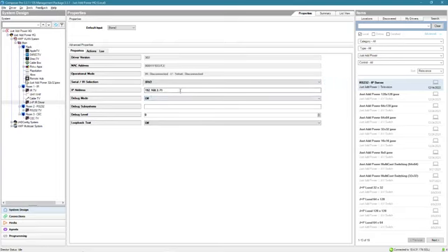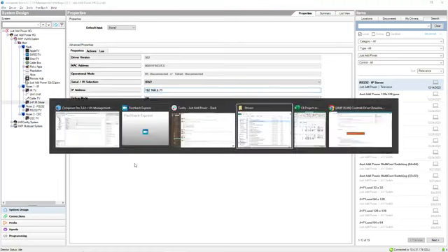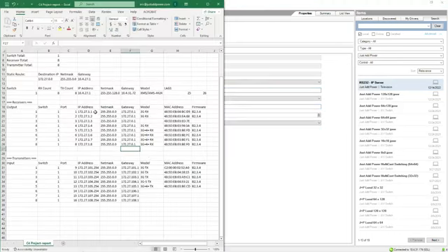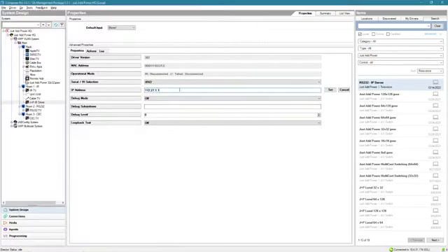And then we need to set the IP address of the Just Add Power receiver behind that television. Again, if we've forgotten, it's on our report file. This is our very first TV. So we're going to take the IP address from that, paste it in, and set. Now you're not going to see any operational mode change other than a really brief connect disconnect. This is only going to change when you're actually sending a command. So that's part one. We've got our serial IR and our IP address.